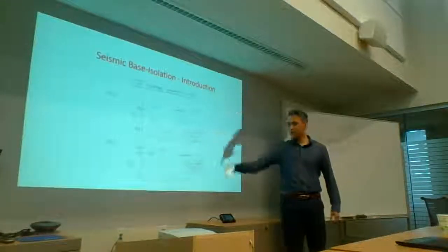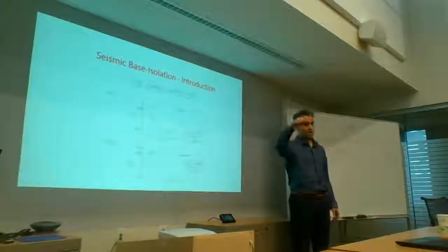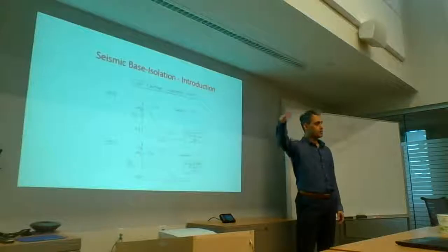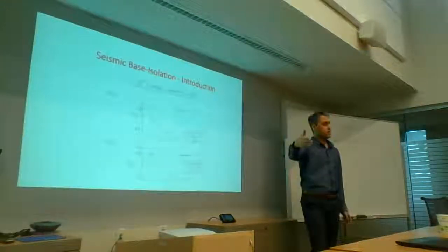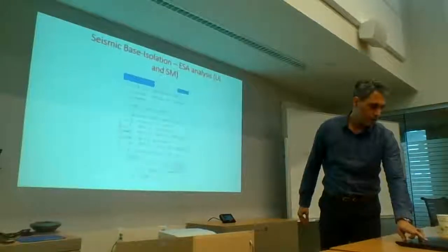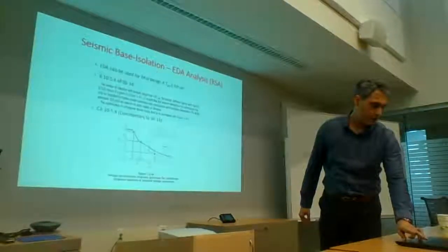This is not a very typical response spectrum, but a lot of the times you see in actual earthquake response spectra that there is a second and a third kick at longer periods. So you want to be mindful of that. Okay, so that's just it about this.